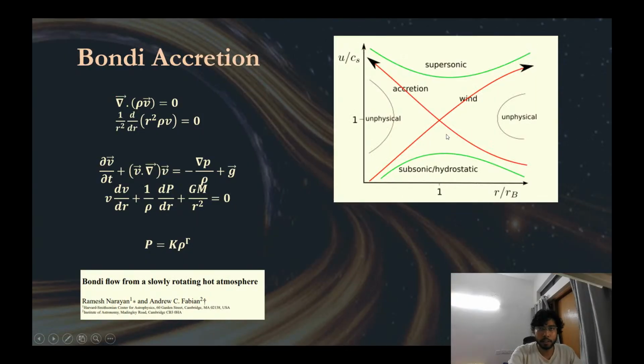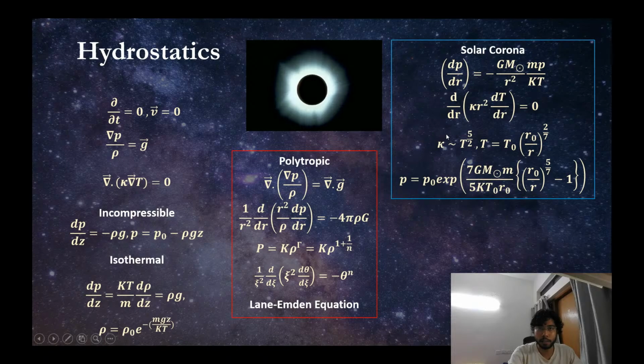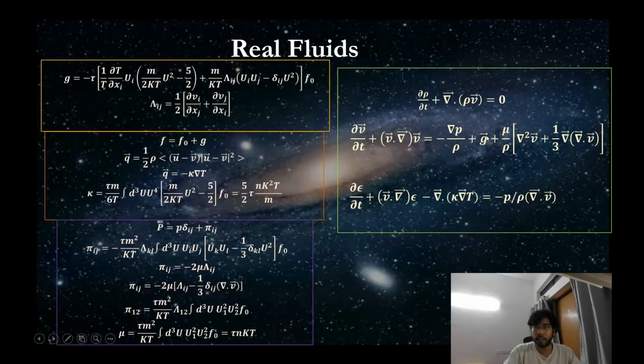If you remember this equation, yeah, this Navier-Stokes equation, you see this is the term for the viscous force, right? Whereas if you write the phi component, or the theta component, of this equation, working in cylindrical coordinates, so it will be r, theta, z, whatever factor is causing the angular momentum change will show up.